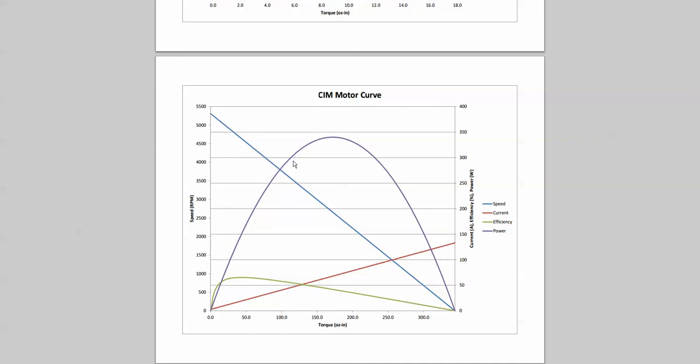But if you can gear something 10 to 20% faster, and that speed advantage is actually resulting in higher performance on the field, more points, that sort of thing, then replacing motors might not be crazy for you. But certainly you don't want to be designing for that point if you don't have a good grasp on your system, because it's real easy to miss that and have something that's going to burn out the motors all the time.